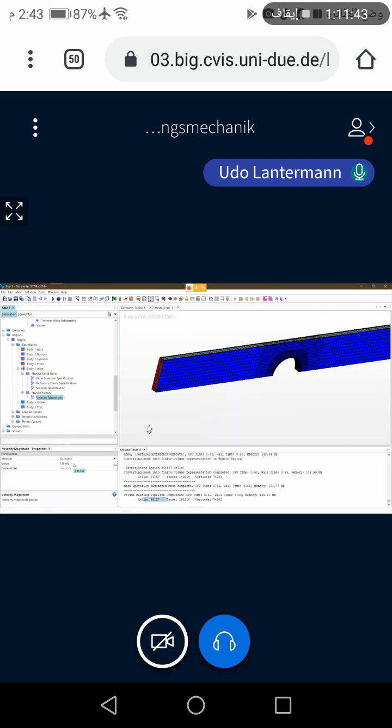The default one is 1 meter per second, and we will choose also 1 meter per second. So here we also use this default value, okay? But here you can set, if you want to have a higher speed, then you can set it to 10 meters per second or a lower one or what else, okay? So in this position, you will define your inflow velocity.